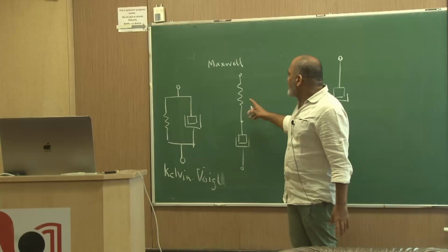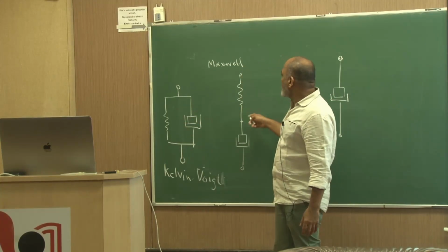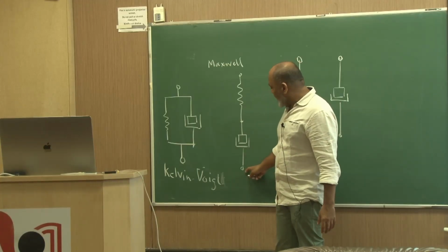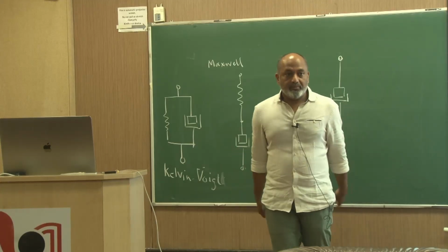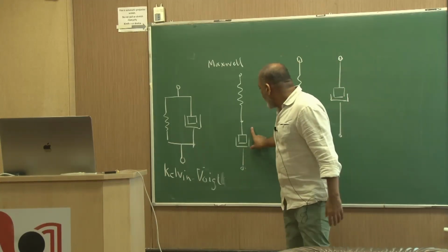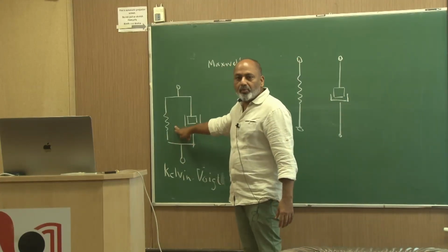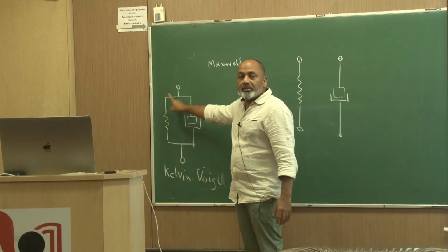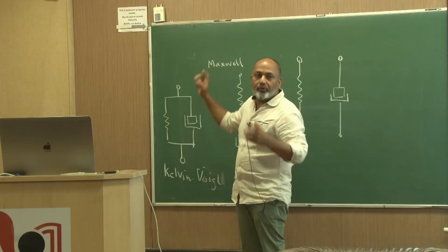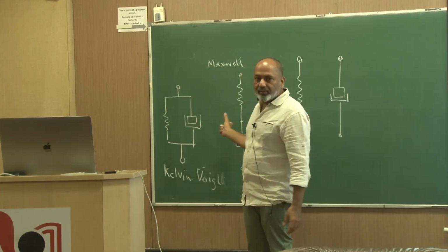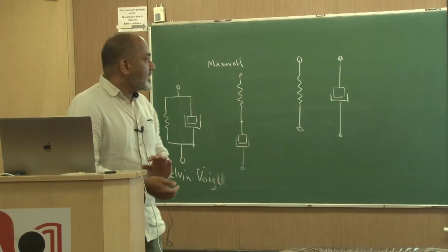Well, if you really think about it, this approaches solid-like behavior and this approaches liquid-like behavior, because if I apply stress, if I apply force on this, then the creep is infinite, because the deformation will keep on happening. And if we put it in this way, then this will always resist any further deformation, so it is not going to elongate forever. So this is something we also have to see, what difference one is keeping in mind.